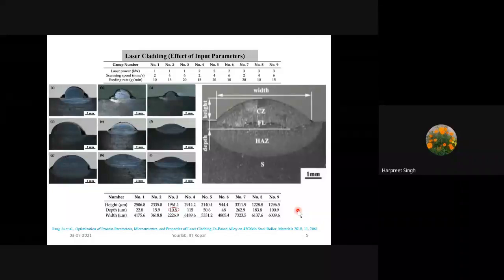Now here is laser cladding. As I said, one of the disadvantages we face here is this HAZ, the heat affected zone. This is something we are worried about. Suppose you deposit copper here. Yes, the coating is very dense; that's not a problem. But the problem is this HAZ which we produce in our substrate material, right?